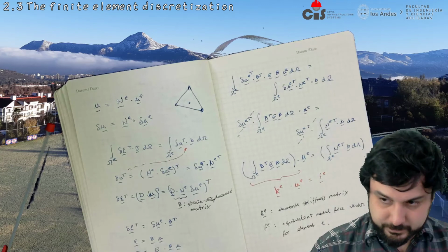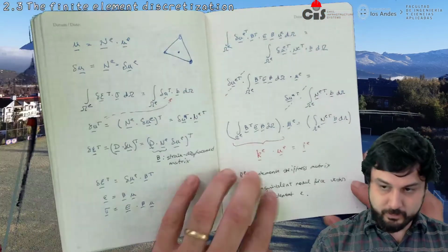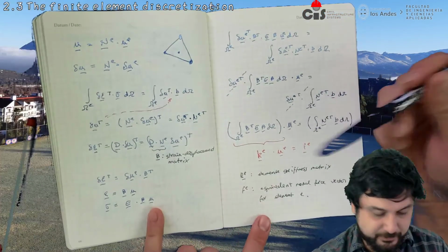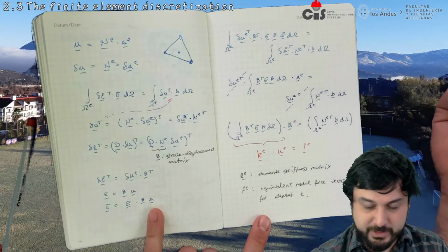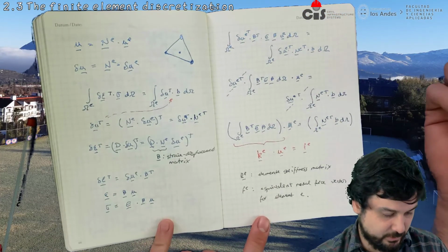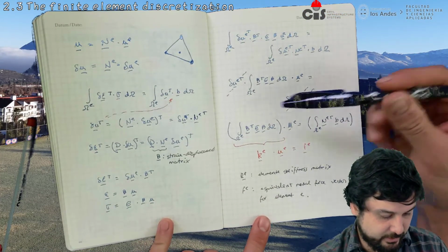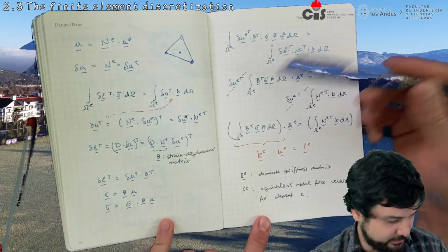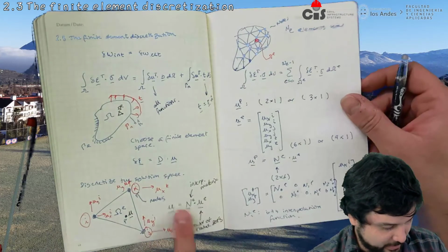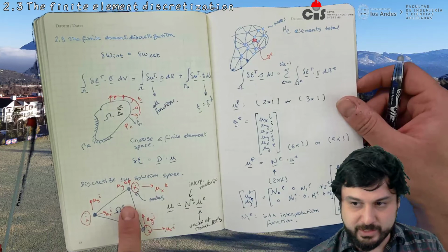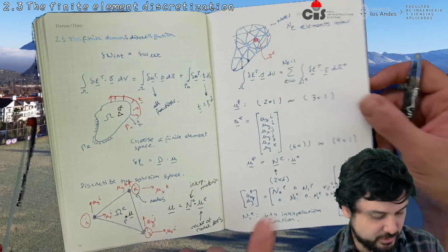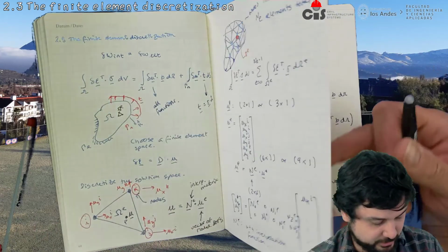So then we can write the stiffness of an element by using these equations, which we will specialize in what comes. Here the value of B and N are going to depend on how exactly you do this interpolation inside, how many nodes you have, and what are the options here. There are a bunch of options you can have.